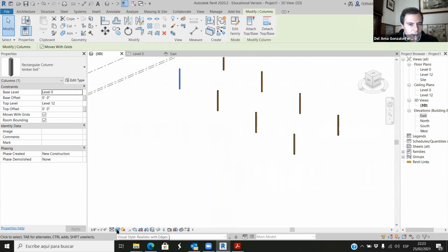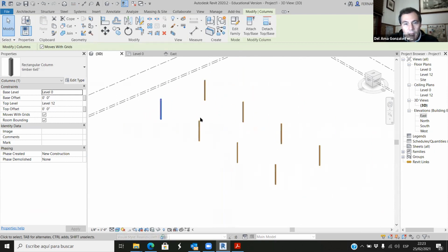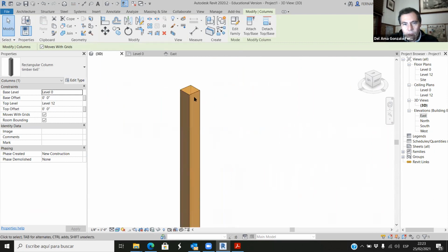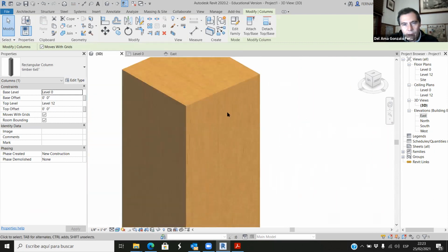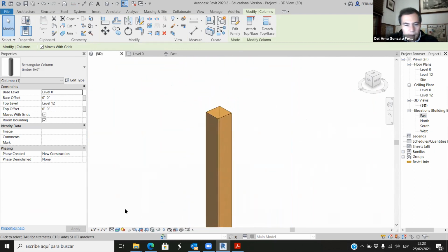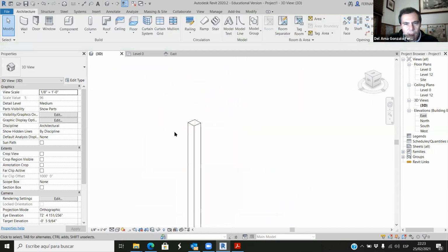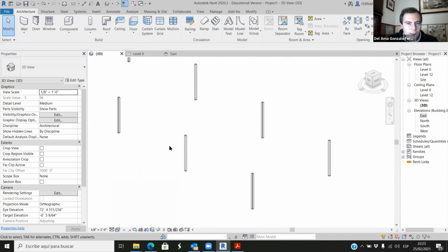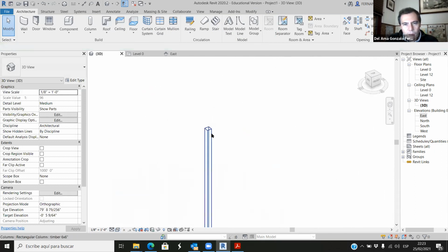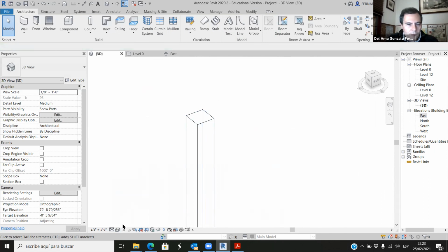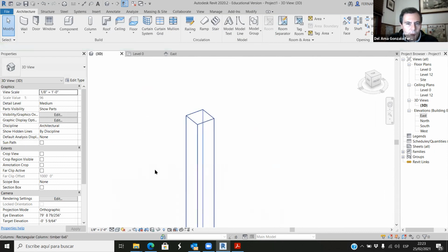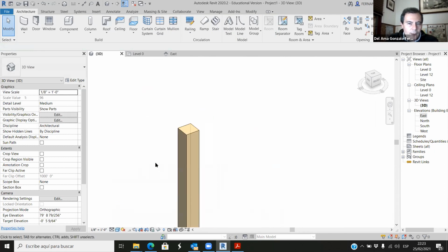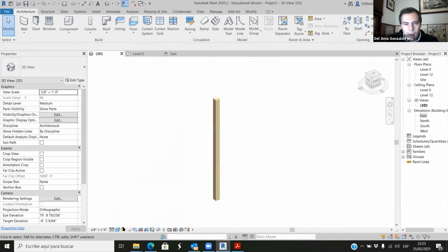Oh, by the way, these are the visual styles. So I have these visual styles by default. So you see the actual color, and even the texture of this, I'd rather use a hidden line. Okay, but here you can change the way you visualize things. With a wireframe, you can see that the objects are like transparent. With a hidden line, we don't have this transparency. And then you have different things, realistic, shaded. For rendering, we can use this, but for working, I think it's better using either wireframe or hidden line.